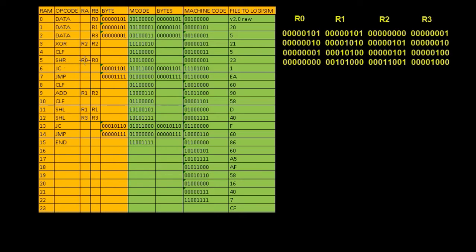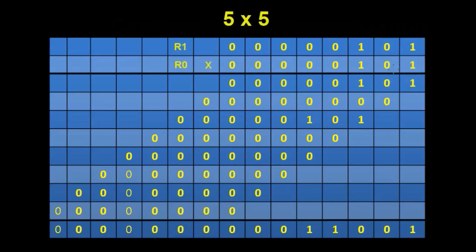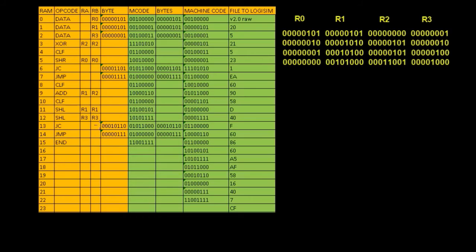So it takes the register R0 and again it shifts it to the right. So when we have a look at R0 here, R0 this time is going to have the value 0 at that point. So when it gets shifted to the right, it's going to shift out a 0. So if it's shifted out a 0, now we know the carry's not going to be set. So it's jump if carry to that line, so that doesn't occur. So what happens is it goes on to the next line and it actually jumps now to this point here.